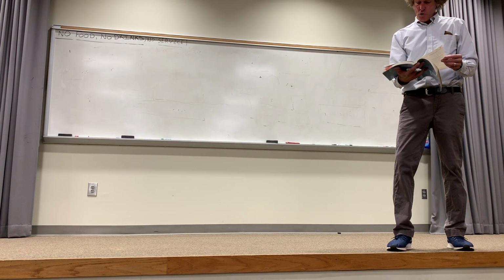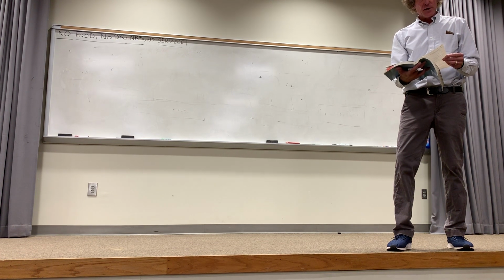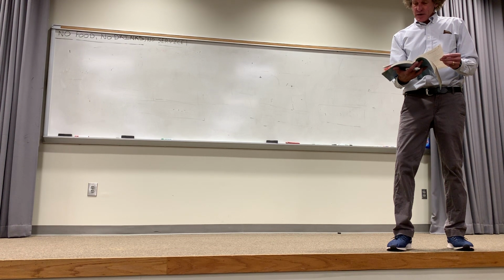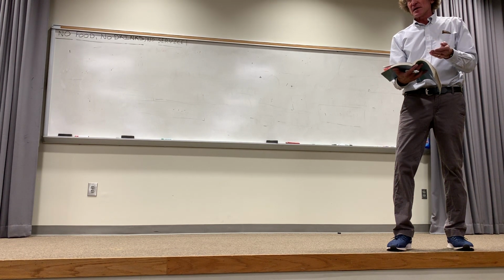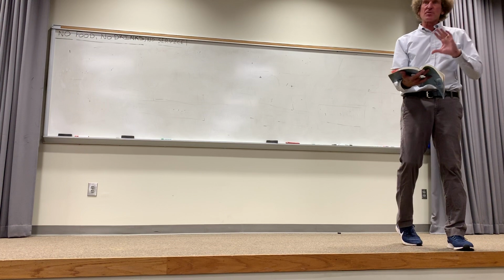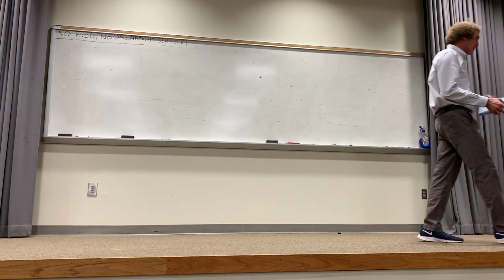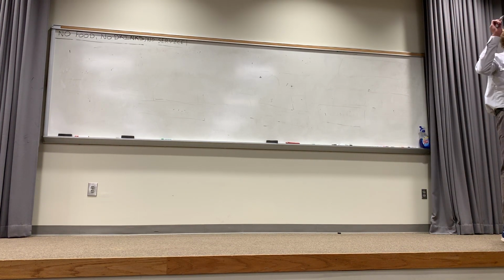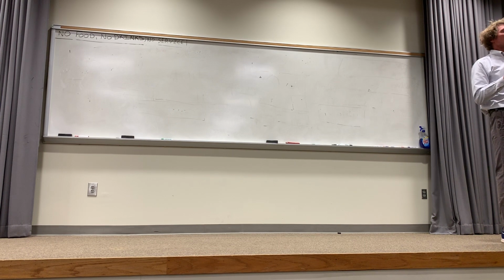The last bit of homework is going to be from 6.30 to 6.33. So there's 4 problems, 6.30 to 6.33, and I can tell you right now, they're not tricky if you do them the way I said. First, these are transformer problems, so write the equations for output to input voltage, output to input current. Remember, current goes into the dot, voltage is plus at the dot. And I've held you up before, so I got about 149.